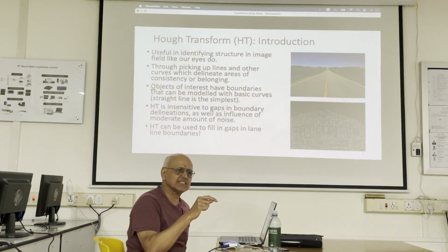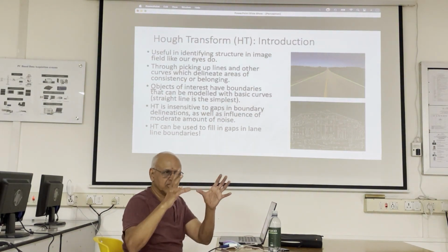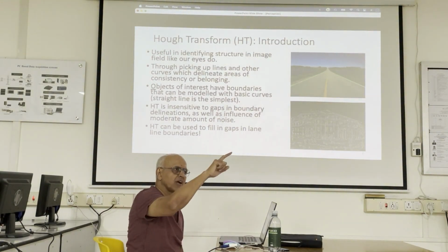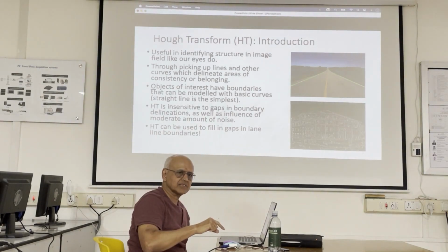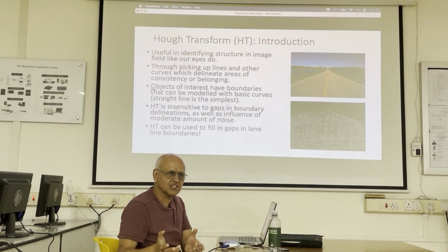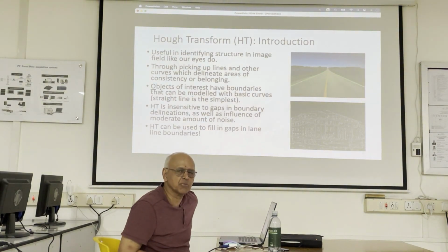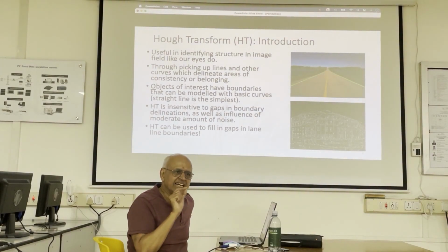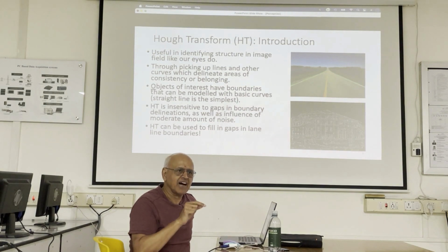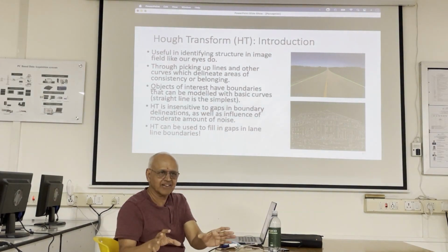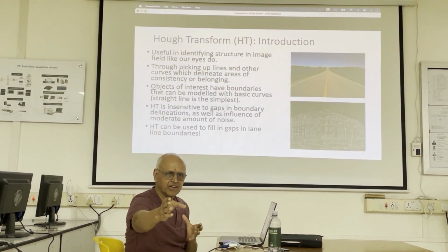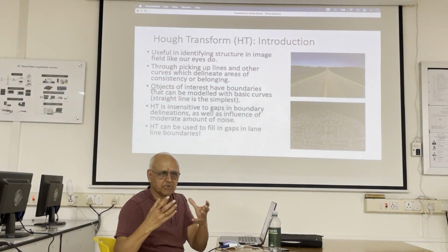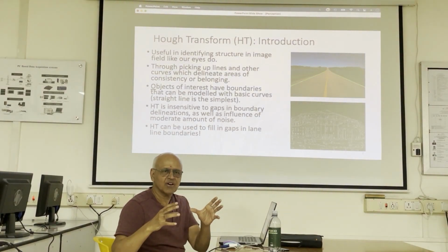You check for changes in pixel intensity. So images are in terms of pixels. They are pixel elements. So 512 by 512 means that you have 512 like this and 512 like this. Nowadays we have many more than that. You have HD and 4K and all that, right? So it's much more sophisticated. But essentially, you're looking for changes in contrast. So edge detection is based on changes of contrast. Until you find the edges, you can't decompose the scene. That's how you see things. The camera is different from you, right? So that's what results in perception, converting the scene into meaning.